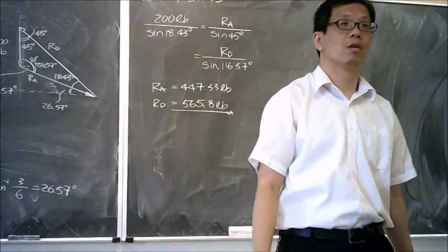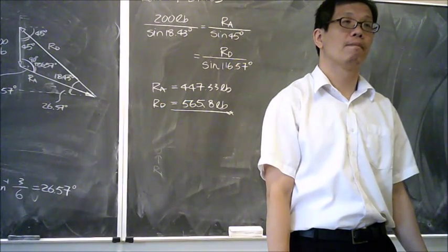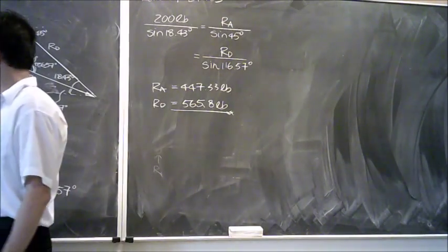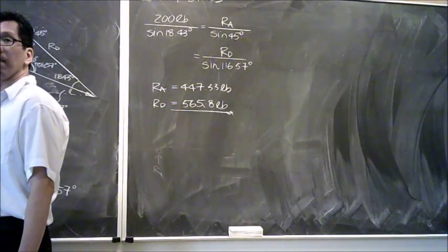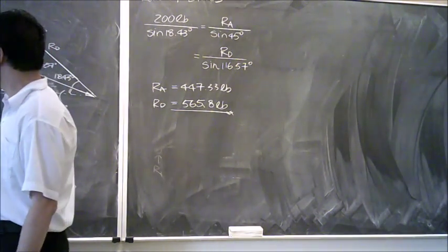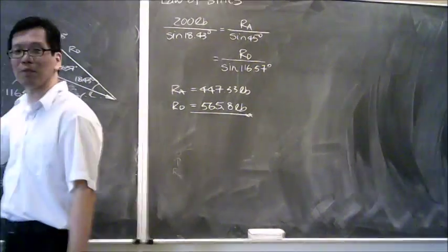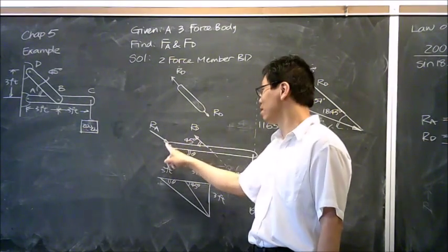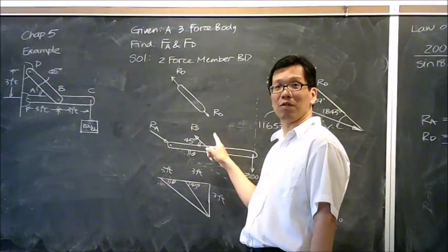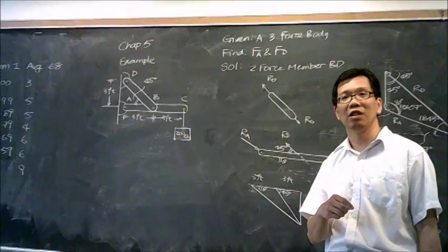Can you take that 3-body diagram, and if you're not going to use the geometry method, if you're going to use the other method, can you break it up into the second diagram where you only have the one? Can you sum your forces and moments from that? Yes. You probably want to do your moment center at this point because over here you have 2 forces, but one of them is not going to create any moment, because Rx is not going to have any moment contribution to the configuration over here. Okay. That's a good question. Any other question? No? Okay.